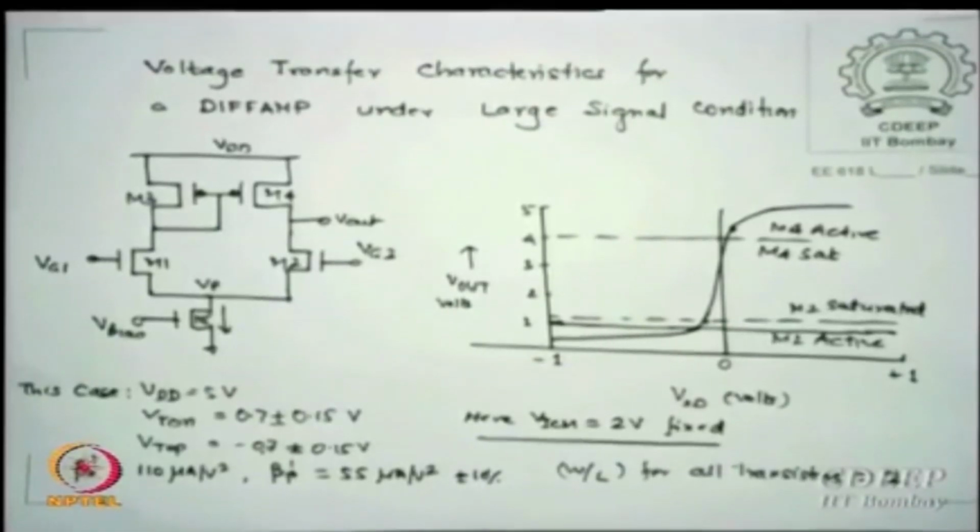So do not come and say, sir, that is fixed, you can always change your spec of your choice by putting another model card there. I am not sure with NG SPICE or SPICE 2G 3.3 has that, but just figure it out. The model card allows you to specify all mu's, TOX, everything of your choice. Okay. So please take it, these are some issues of interest.